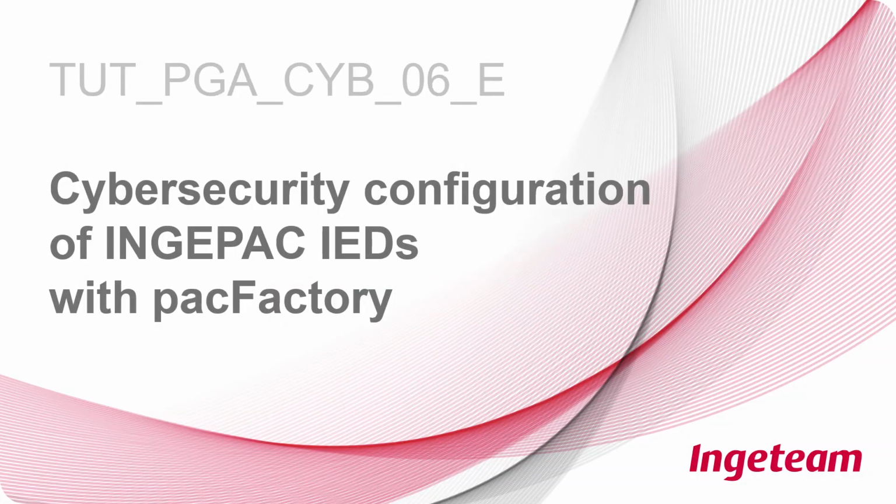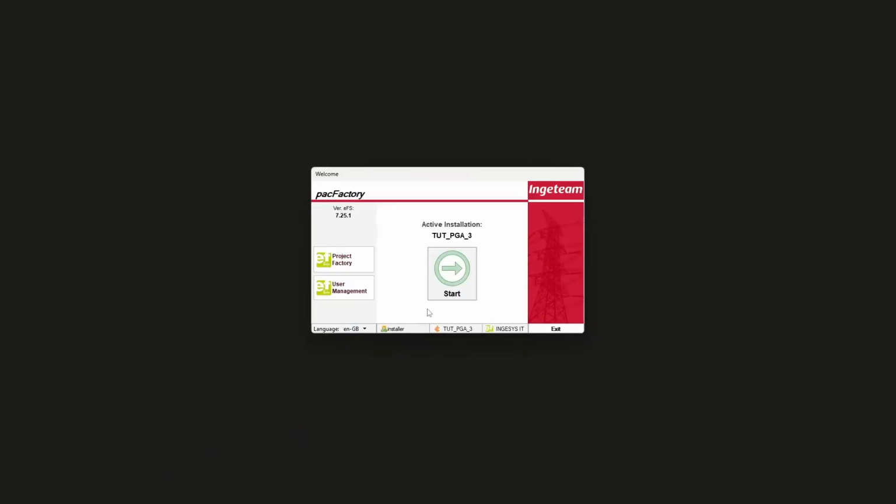Tutorials. Topic: Cybersecurity configuration of INGEPAC IEDs with pacFactory. In this video, we will learn how to configure the cybersecurity settings of an INGEPAC IED with the INGEFactory Suite tool. We will launch the pacFactory application and open the IED list view of our active installation.